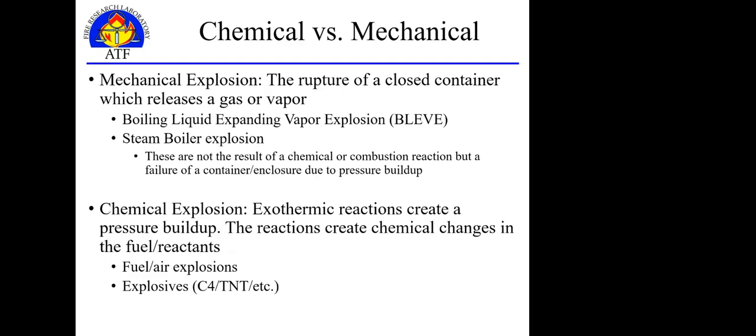These mechanical explosions aren't a result of some sort of combustion reaction or chemical reaction inside the container. It's just pressure buildup in the container that results in a failure of the container. In the case of a BLEVE, we often see those with propane cylinders.